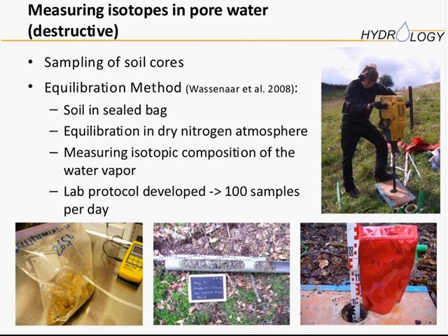The next one, and Les already told you a bit about that last week, is those pore water equilibrium methods. We also use that a lot, and we have more or less set up, I think, a relatively good lab protocol. We also moved away from the standard Ziploc bags that you can see on the left, and now we are using more gas-tight bags. That seems to be especially more reliable when we want to store the samples not only a day or two, but for a longer time, and that works very well.